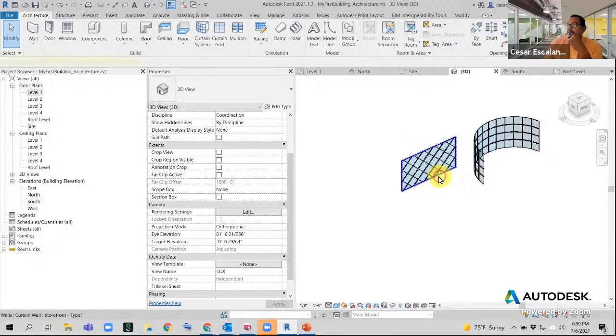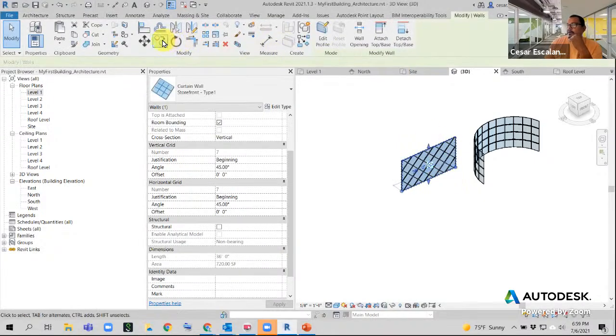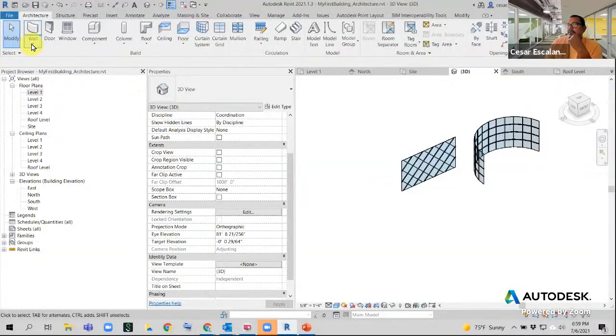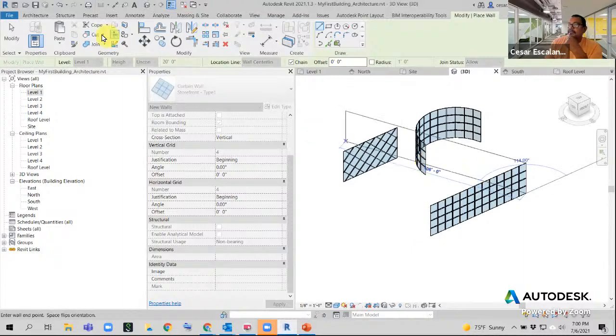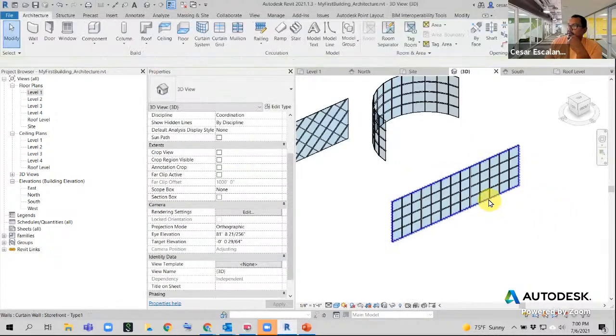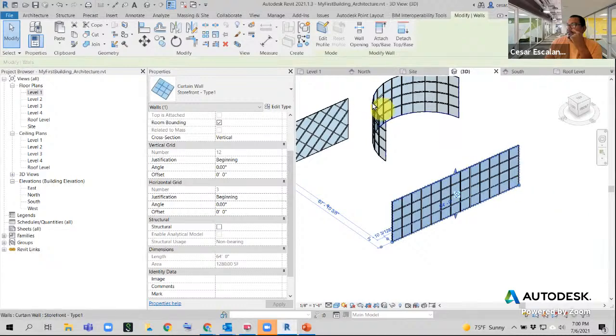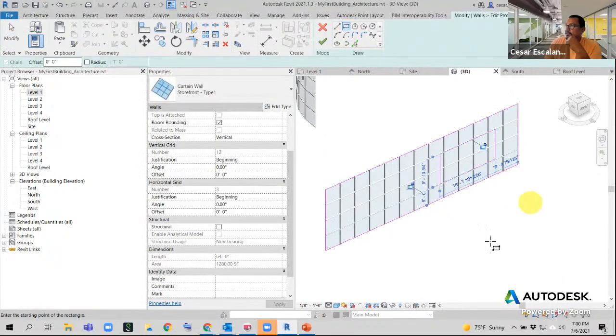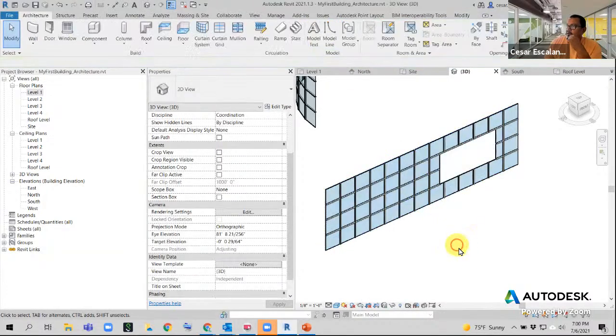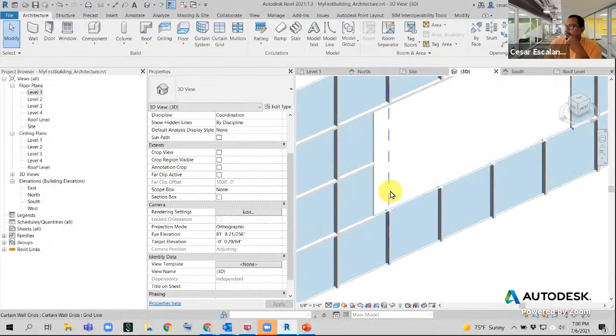And also you can edit the profile of walls. I'm going to create another wall here using the same type, but now I'm going to edit the profile. Select the wall, edit the profile, and I'm going to do, let's say, a rectangle, an opening inside another opening. This is just a sketch rectangle inside of the other one. Click the checkbox, and now I have a wall opening.